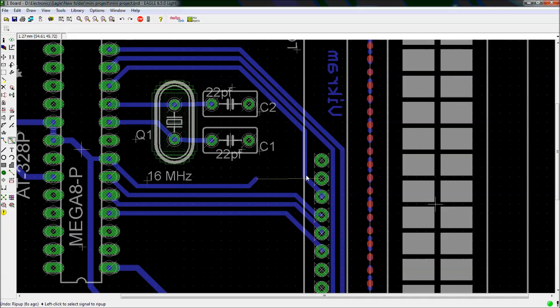So what we can do, we can go for another layer of PCB. If a double layer PCB is available with you, then quite okay. If not, then you can connect an overhead wire to these points. For that you will need one drill over here.